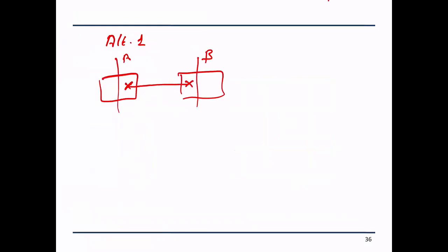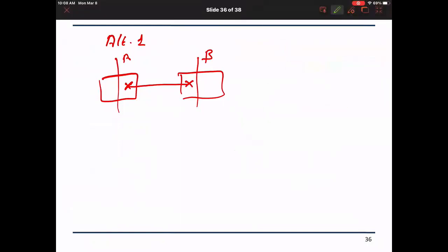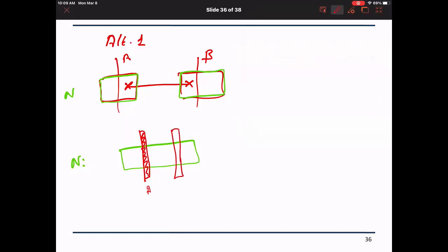between them, right? So actually what we have here is we had the diffusion for the NMOS. Let us assume that these were the NMOSs, and the diffusion for the second NMOS. They are separate, right? And then I have to build contacts and go up and connect them with the metal. An equivalent circuit in the N would also have been what? For me to draw A, right? And B are these two transistors.